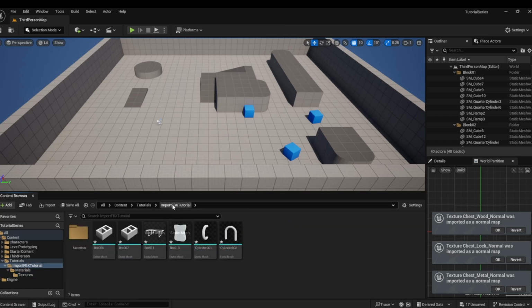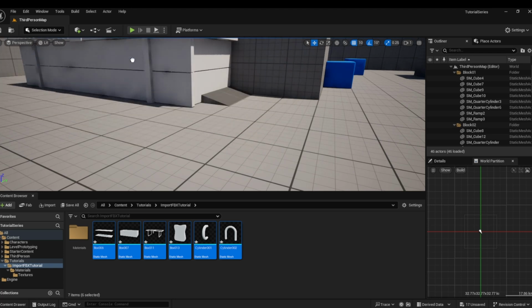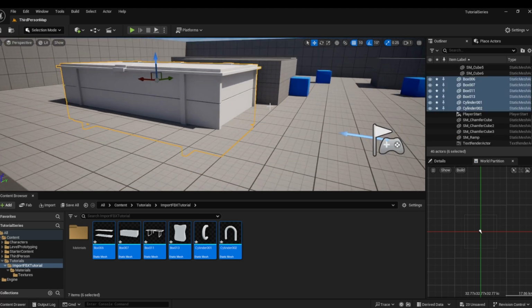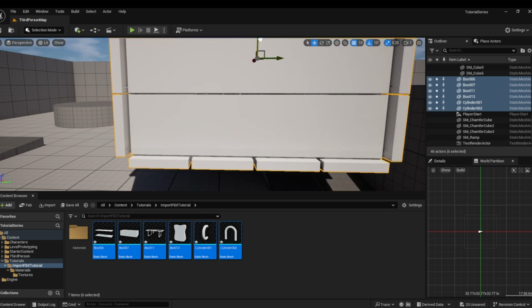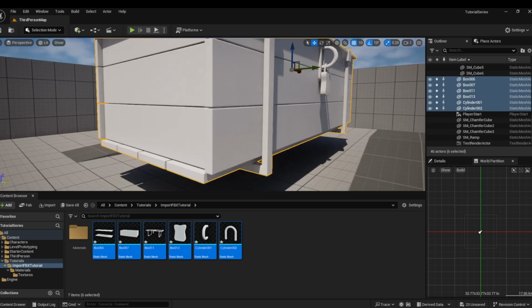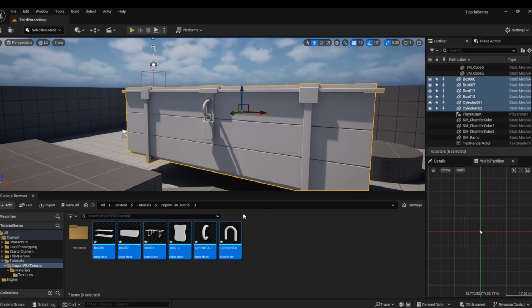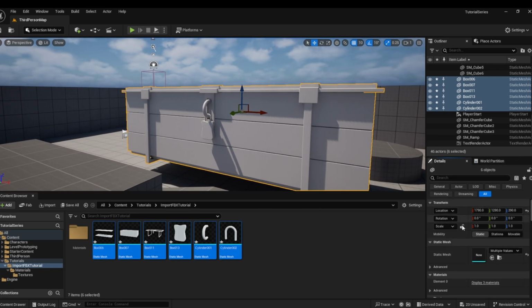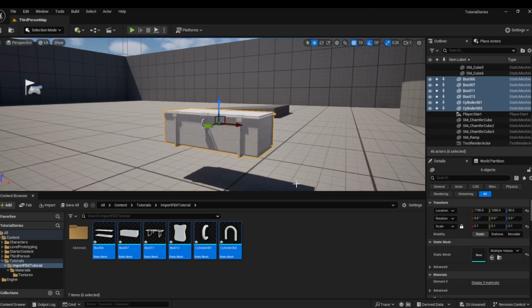Let's place our object in the scene by highlighting all the static meshes and dragging them onto the level. You will see that the size is quite big. This is usually out by a factor of 10. To fix, make sure that the objects are selected and go to the Details panel. Select the lock icon in the locked position for scale, and set the value from 1 to 0.1. To focus on your object, you can press the F key.